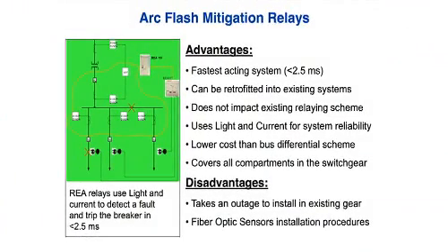One of the opportunities that all of us have, whether in a non-arc resistant world or an arc resistant world, is how do we clear these faults faster? And this is the solution. The REA relay optically looks at the light source. This light source is bright enough that we see it and cause a trip signal to go out through high-speed contacts in 2.5 milliseconds.